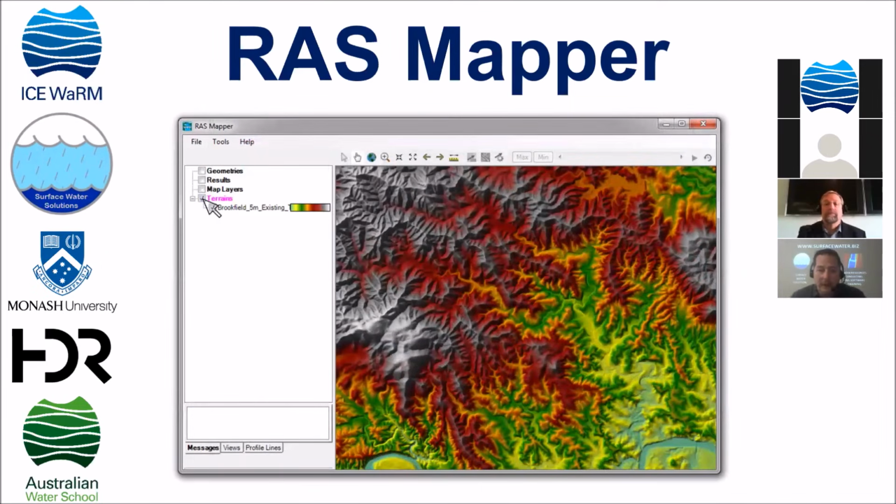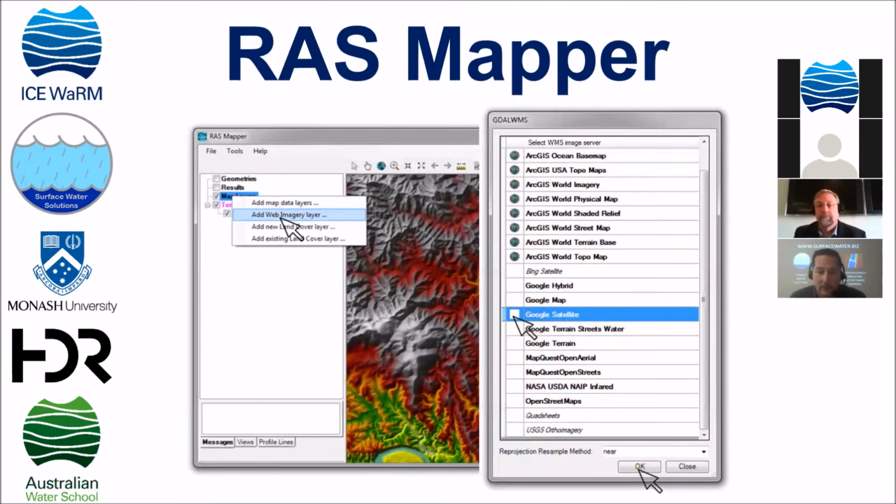You can see the raster information in the background that's color-coded. Now I can mess around with all of the color coding and the elevation ranges, much like you can in any GIS software. Go on to the next slide and we'll see what we can do now with Google Earth and with Bing imagery. One exciting feature is if you're in the right place on the planet, and this is a good way to check your model, find out if you're in the right place before you do anything else, click on Google Satellite or Bing Satellites and you add those. On the next slide, you'll see what happens.